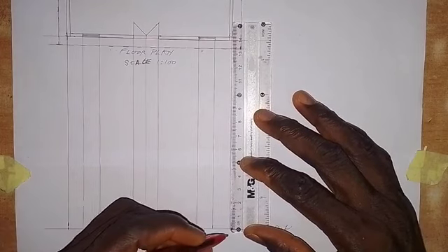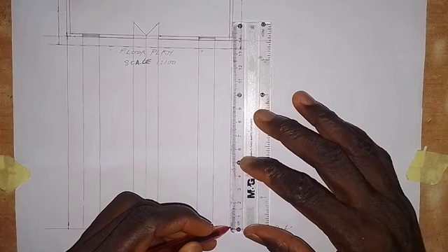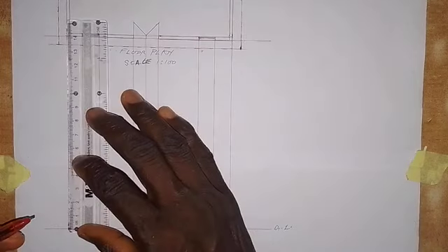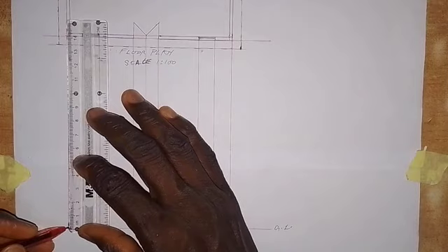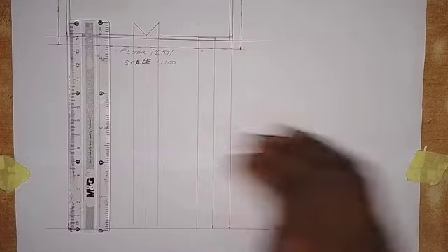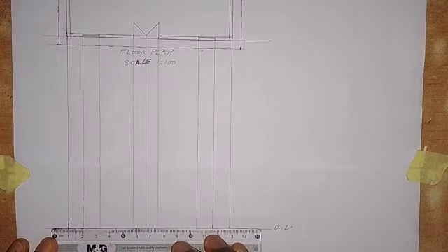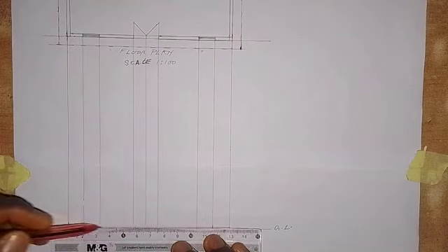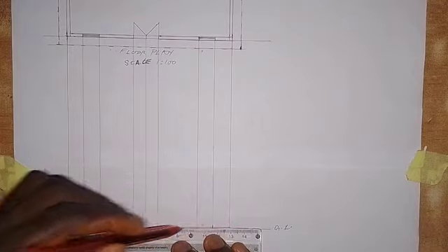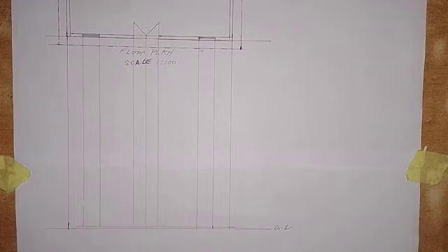Just take a measurement of 1.5 millimeters. I will also come here and take 1.5 millimeters. You can take 1 or 1.5 millimeters. That may not be stated in the specifications, so that's why I do not bring the specifications for this. All you have to do now is to join these 2 points together. This line will represent the floor line or the floor level line. So I'm going to write FL here, so that you know that if you see FL in your objective question, it means floor line or floor level.